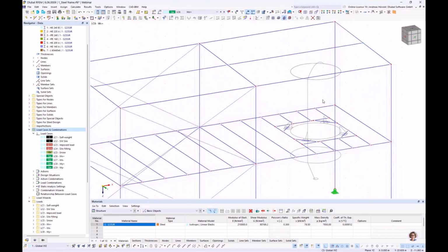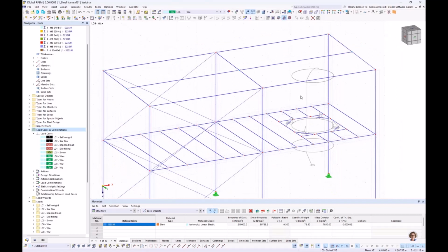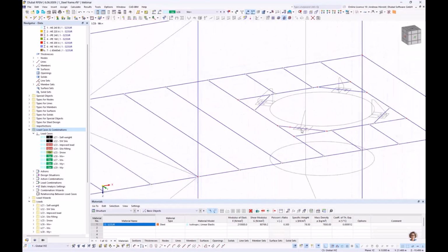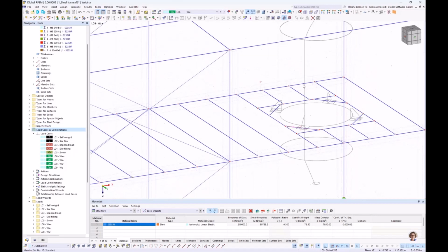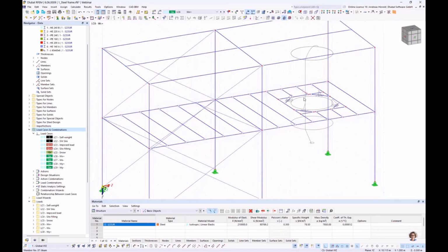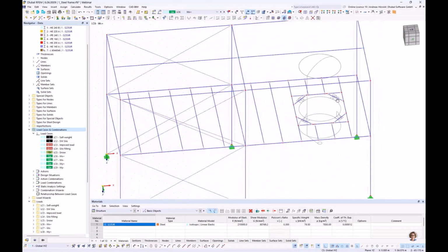That's in that area a doubled load, but I would like to consider also the horizontal load at the beams and also the vertical load from the wind that we get from the moment that we get from the wind on the silo. So I start with the wind in X direction.